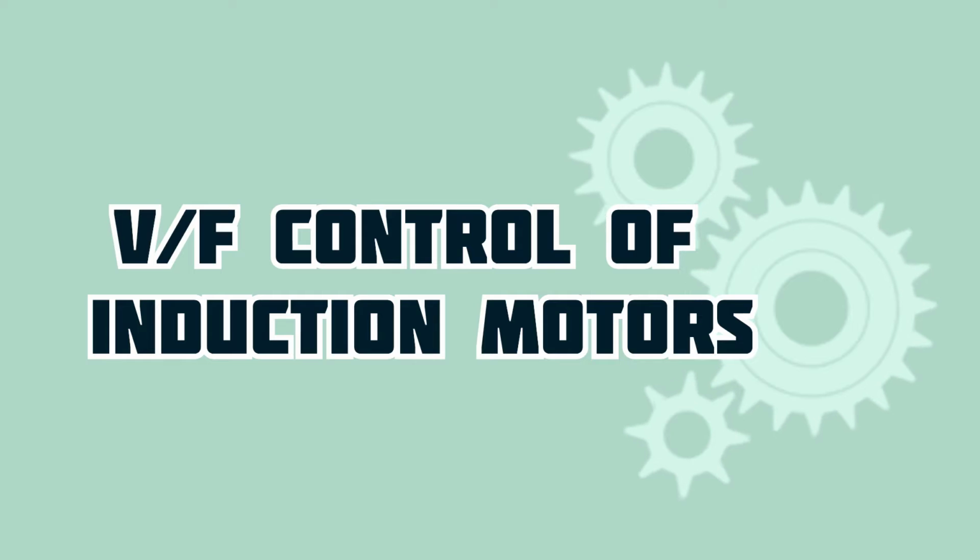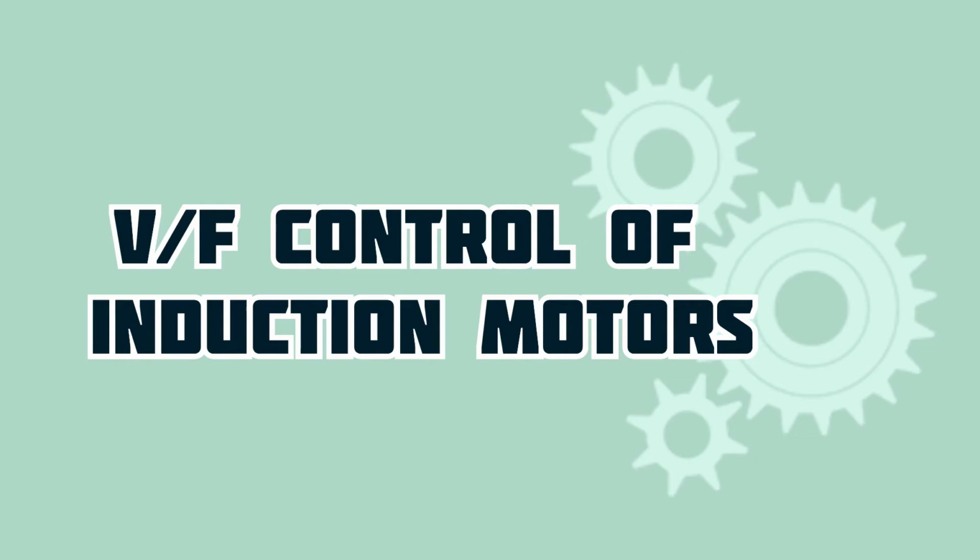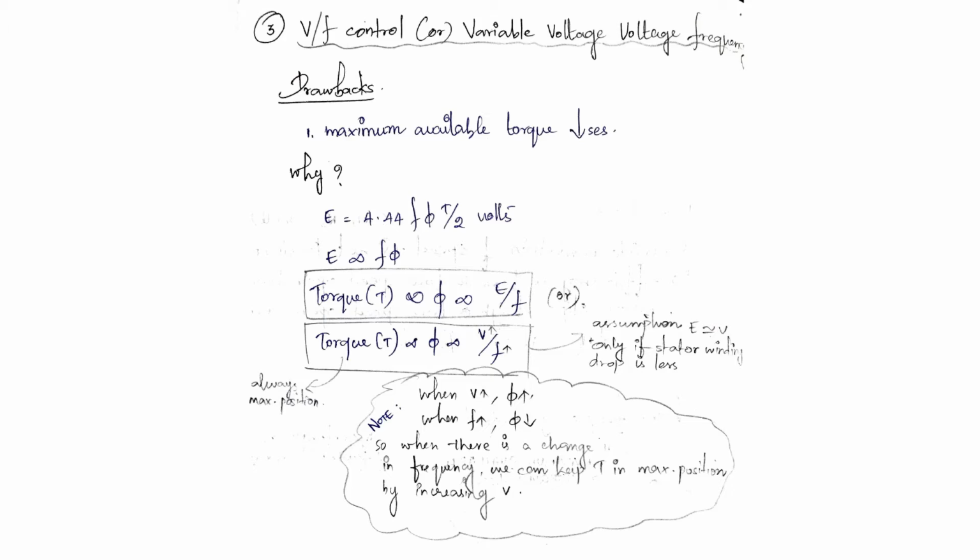Today we are going to learn V by F control of induction motor, which is the most common method in industry to control the speed of induction motors. Here we will maintain the flux and torque by maintaining the V by F ratio as constant. Now we are going to discuss how to maintain the V by F ratio as constant.